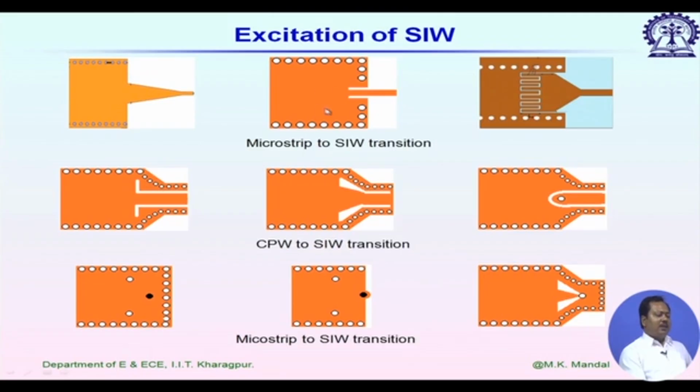Similar designs are possible, and on the right hand side, instead of open circuit, they start with a short circuiting wall. So, it somewhat looks like how we feed a rectangular patch antenna. It is using some inset feeding, and the rightmost one, instead of just simply inset, is actually capacitively coupled. We are using a one finger type capacitive coupling.